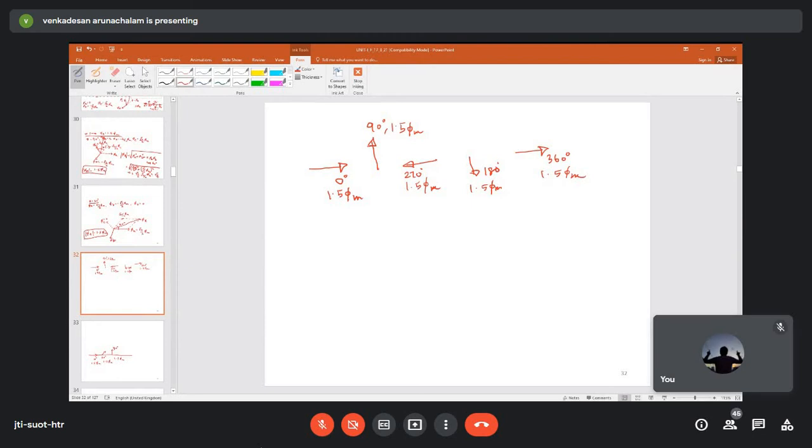So, whenever you give 3-phase input, which is 120 degree time shifted, to the winding which is 120 degree spatially spaced, each phase will give you the magnetic field that is 120 degree phase shifted, and the resultant of all the 3 phases will give you the effect as if it is rotating in the air gap.